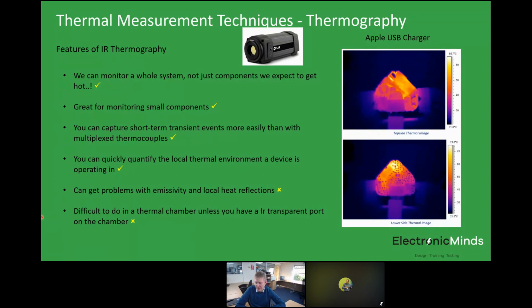So the ambient temperature will depend on the fan airflow rate, etc. So when we run the first test case or iteration, maybe we need to make a guess. Anytime you're going through the design process, you need to assume an external ambient, that's not normally something that's determined in your spec. So I think nothing really beats real physical tests, and this is why it's important to use thermal chambers as well, because if you use a thermal chamber, you can control that external ambient. What you actually see in the field is going to vary massively. So the important thing is that we end up testing to a specification, and that we provide data to show that the performance of the particular power converter meets the requirements if we meet the ambient requirements that are detailed in the specification. So you need to make a bit of a guess, but I don't think that's necessarily a problem.